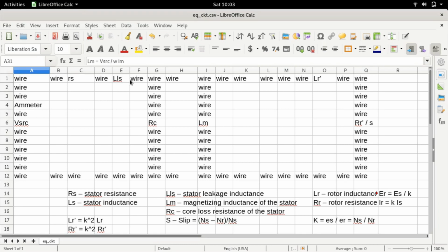So if this motor is, let's say, a 240 volts 5 kilowatt motor, then in that case we calculate the rated current at 5 kilowatt, which is the maximum rated capacity of the motor, and we increase this, we block the rotor, so we don't let the rotor move, right? We physically block the rotor and we increase the voltage such that this rated current is flowing through.